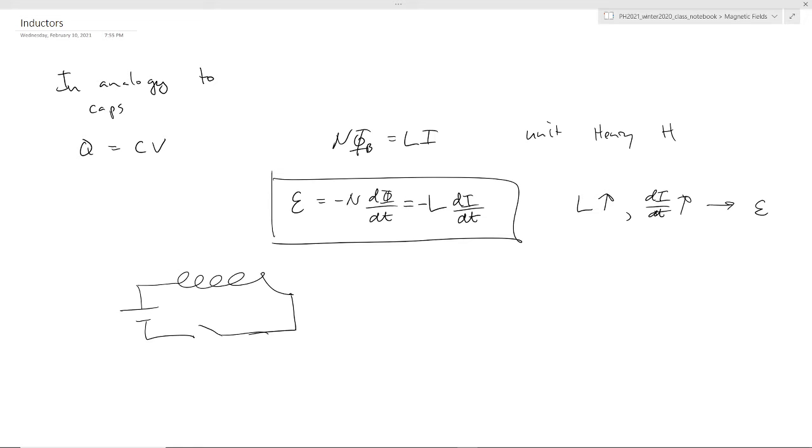That change in current, by disrupting the flow of current, going from current to nothing, will mean that there will be a big voltage generated. And so that can cause a spark on your switch, and that's part of what degrades things like switches in circuits that have a lot of inductance. So that would be something you'd have to be aware of when designing such a circuit.